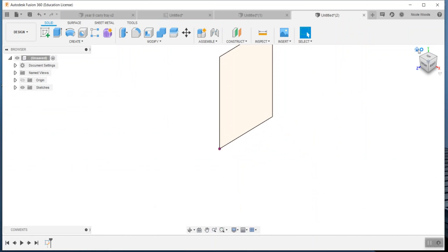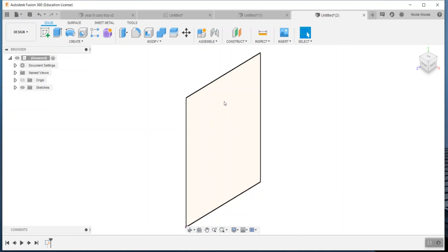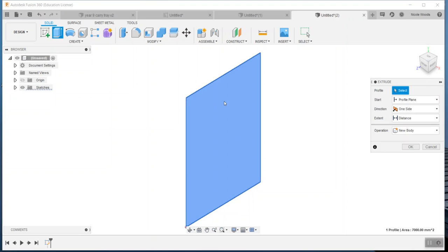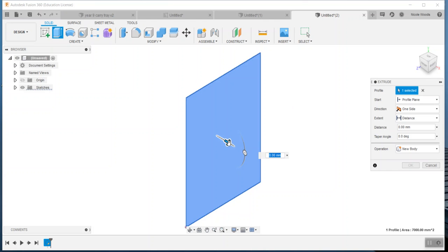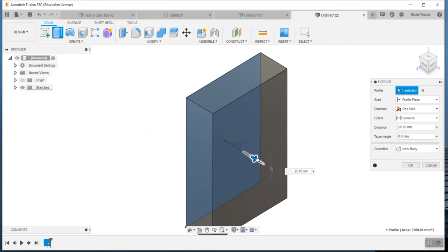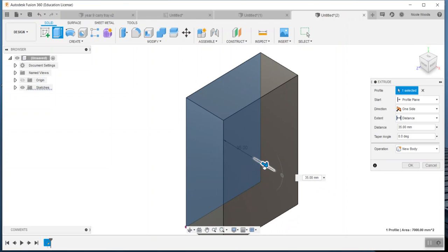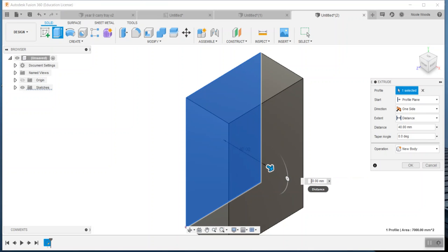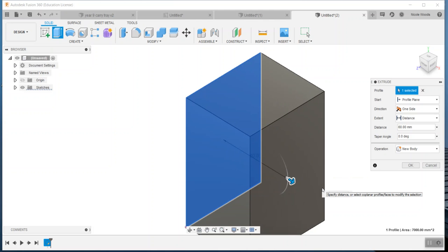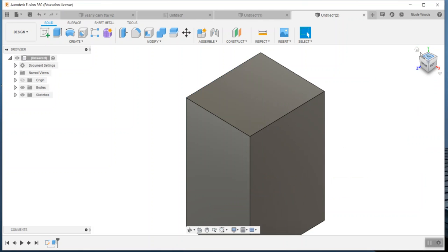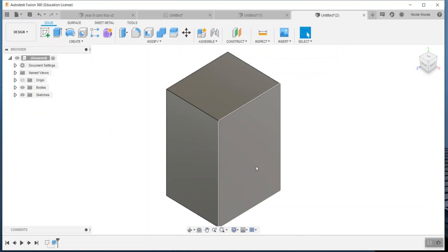Alrighty, now click this house button, brings it down into full view. And if I click E on my keyboard for extrusion, and then I drag the arrow, I can make it 3D. Okay? I can type in this box if I want a specific dimension. Let's make that 60. Enter. Okay? Show everything. Here we go.